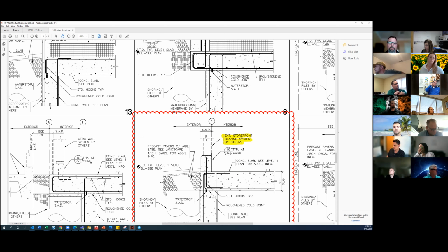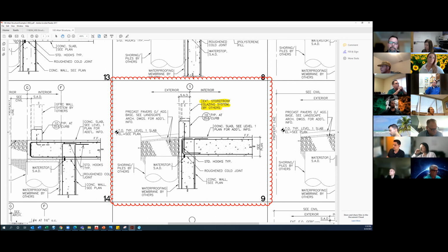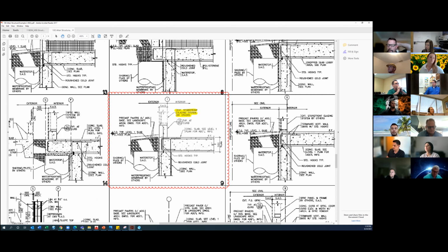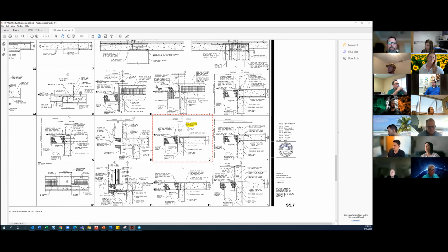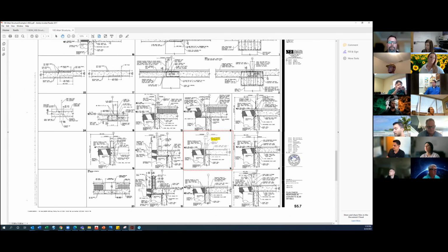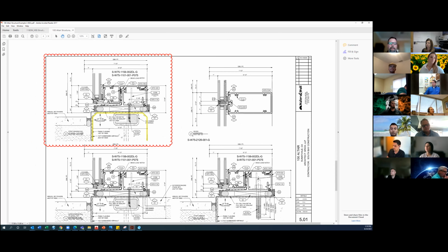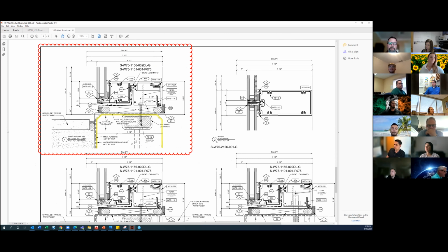the structural drawings. And sure enough, the structural drawings actually show the curb. They show the placement of the curb and where they anticipate our system sitting on that curb. You can see that the back of the system lines up with the back of the curb, and the curb is chamfered, so this is going to be reality. I think too often in the drafting world, we sometimes draw what's convenient or what we think we know. If we don't chase it down, it can be different. And that's the detail that we do have now, because that's reality.